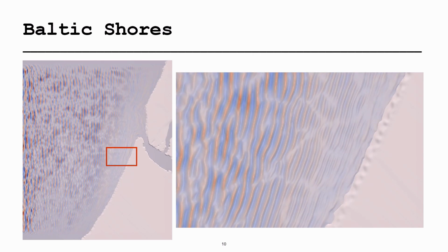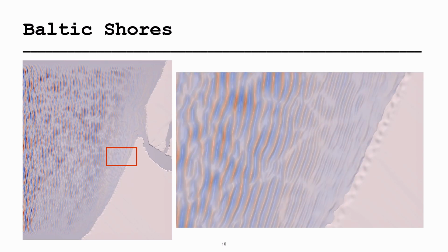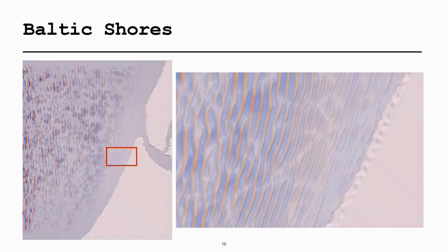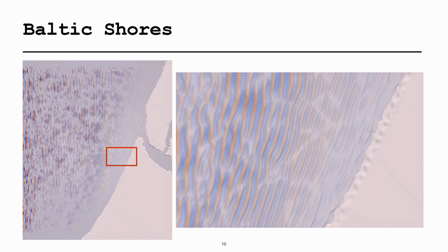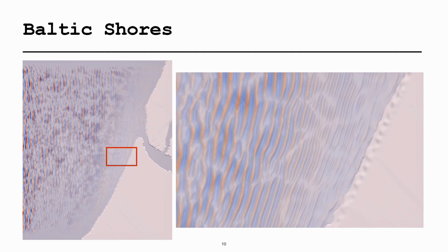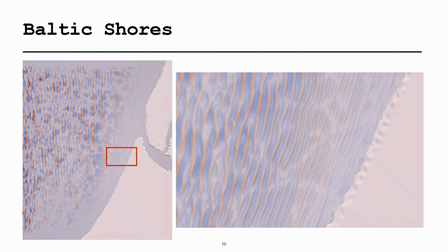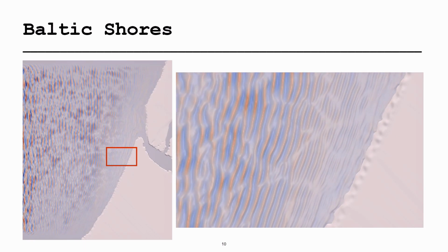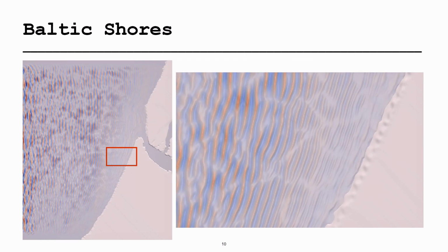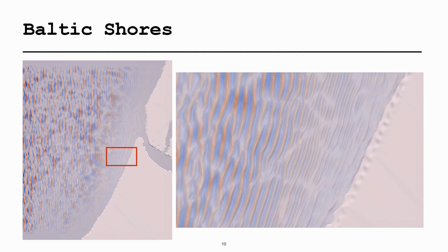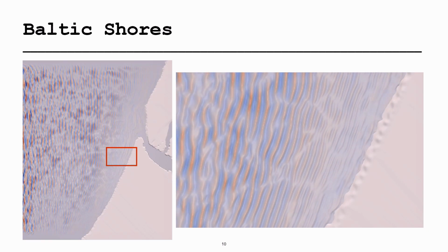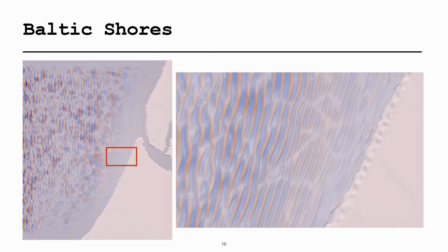And if you also zoom in a little bit more detail to the coast, you can see how the wave propagates. And if you really focus your eyes on the coastline, you can see the waves run up and run down. Basically, the coastline geometry changes over time because of wave run up and run down. That's also, again, the difference between NH flow and FNPF, because in a potential flow model, the coastline is fixed. But in this model, the coastline is not fixed, so we can have the coastline, coast swash zone dynamics.